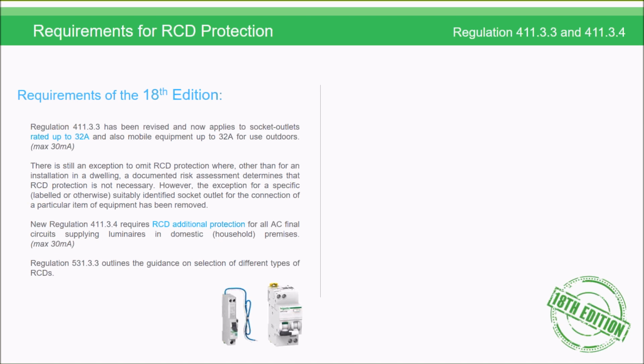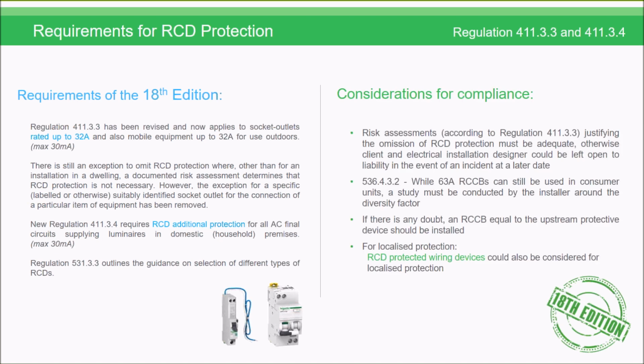In all AC lighting circuits in domestic premises, we require an RCD protection there as well. So in some cases today, RCDs are not required on lighting circuits. However, all circuits in domestic household premises must now have RCD protection.